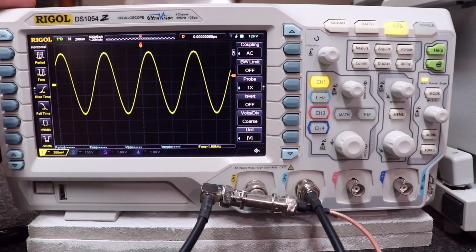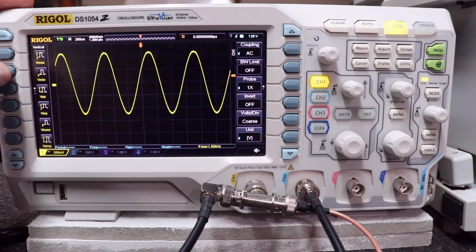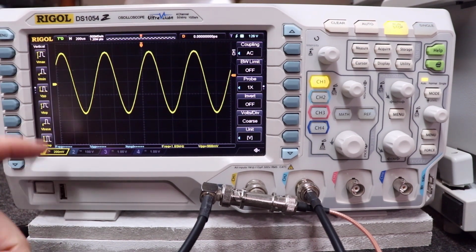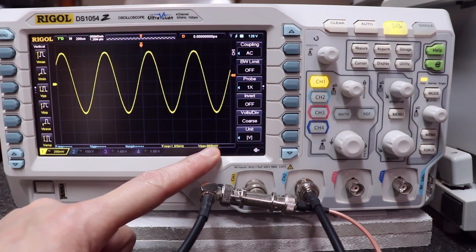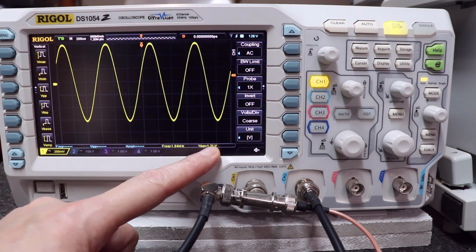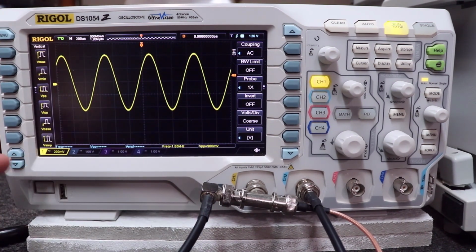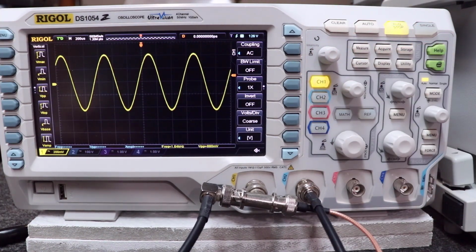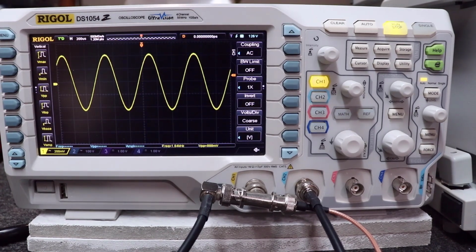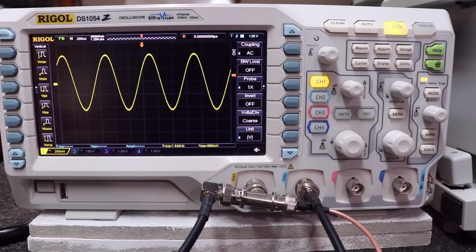Over here on the left, I can click on menu and I can say, hey, I want to measure voltage max or voltage this or voltage peak to peak, okay? As soon as I click on voltage peak to peak there, now I'm measuring my voltage peak to peak. And as I vary that voltage, watch it. It'll read instantly what's going on over here. So these are just really smart units, but keep in mind, everything's kind of menu driven versus knob driven. So I actually think the learning curve is a little longer because you have to learn the various menu functions, and some of these are 2 or 3 or 4 steps deep in the menu.